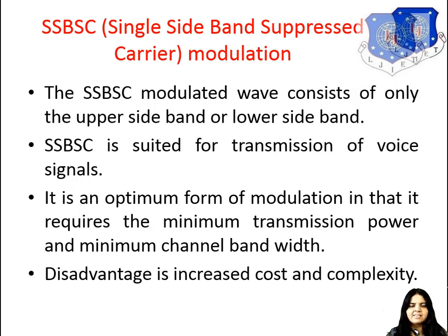So the SSB modulated wave consists of only the upper sideband or the lower sideband. SSBSC is suited for the transmission of voice signals. It is an optimum form of modulation in that it requires the minimum transmission power and minimum channel bandwidth.